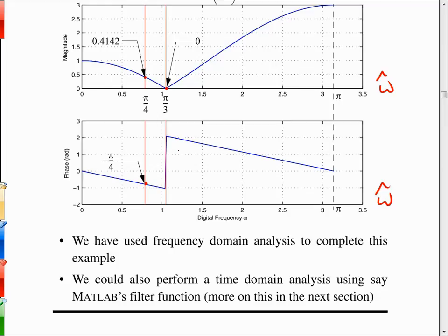I worked on a system like that that was going on the nose cone of a cruise missile, and it was an adaptive filter so that as the missile was flying, this was during Desert Storm, if you remember, that was the first application of smart bombs, and they were targeting certain locations, but they were using GPS, and GPS is not jam resistant entirely, so plus an inertial navigation system was on board, so they fused data from those two systems to stay on target. But the idea was to have an adaptive antenna array that could steer a null in the direction of a jammer, which might be a high power source on the ground trying to confuse the smart bomb as to where it's going to go. You adaptively have to steer the beam because as it's in flight, the angle that you want to take the jammer out at is going to be changing.